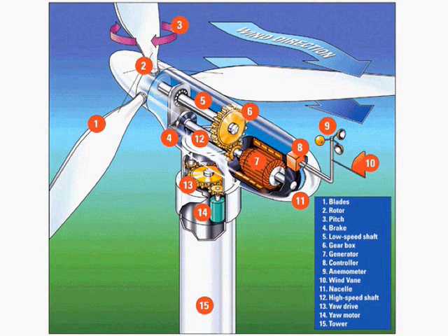The nacelle, it's a French term referring to a boat, and this is where the guts of the machinery are located. And so you'll see lots of gearing. The gearing is very important because say a typical turbine might spin at about 12 to 15 times per minute, you can ramp that up to thousands of RPM using gears, and that is better for producing electricity.